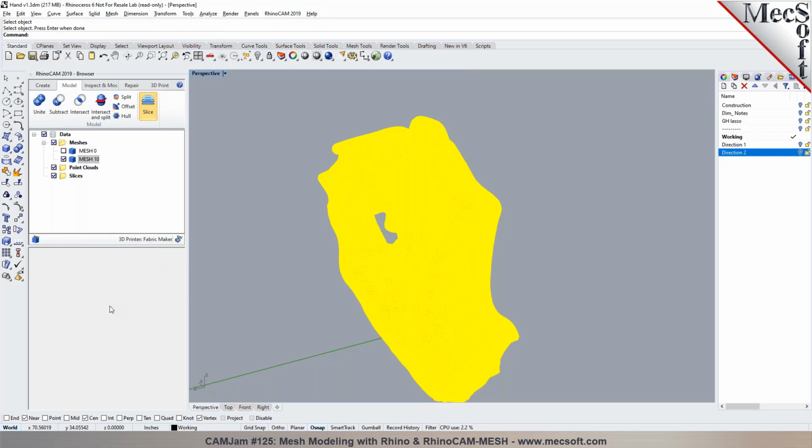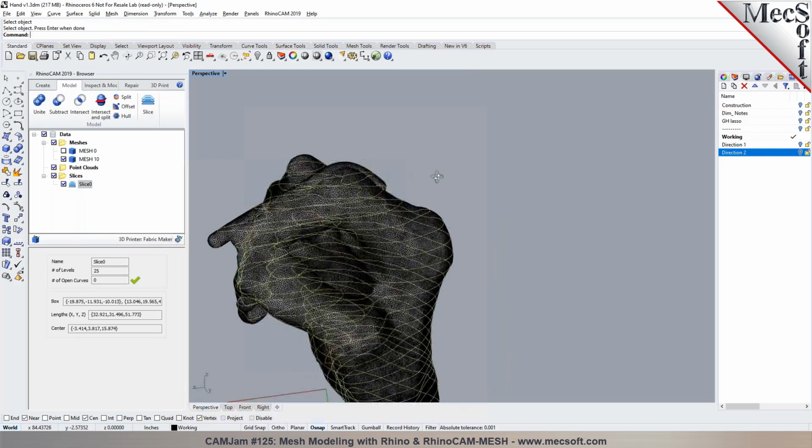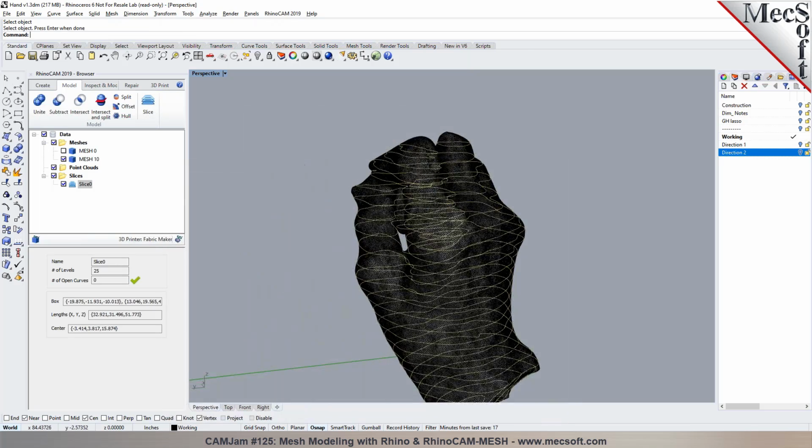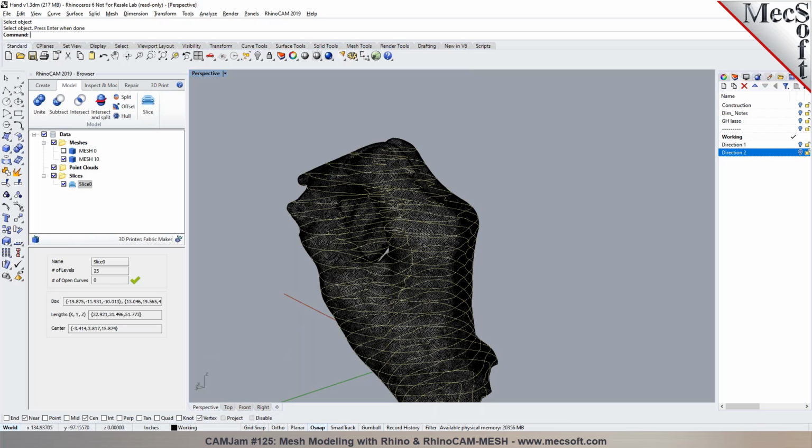It slices it parallel to the plane that you're in and creates these slices for you. You can export them as Rhino curves, the slices. Oh, no kidding. And then if you want to actually machine it, you can use them as splitting points. You can slice them and then put it on your sheet to machine it. Because these are all parallel, constant z.